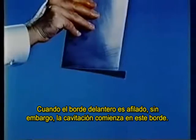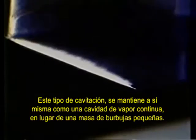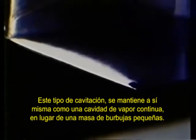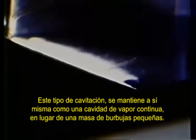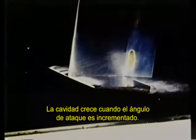When the leading edge is sharp, however, cavitation begins at this edge. This type of cavitation maintains itself as a continuous vapor-filled cavity, rather than a mass of small individual bubbles. Its size depends on the angle of attack, the ambient pressure, and the flow speed. The cavity grows when the angle of attack is increased. It also grows when the ambient pressure is reduced.